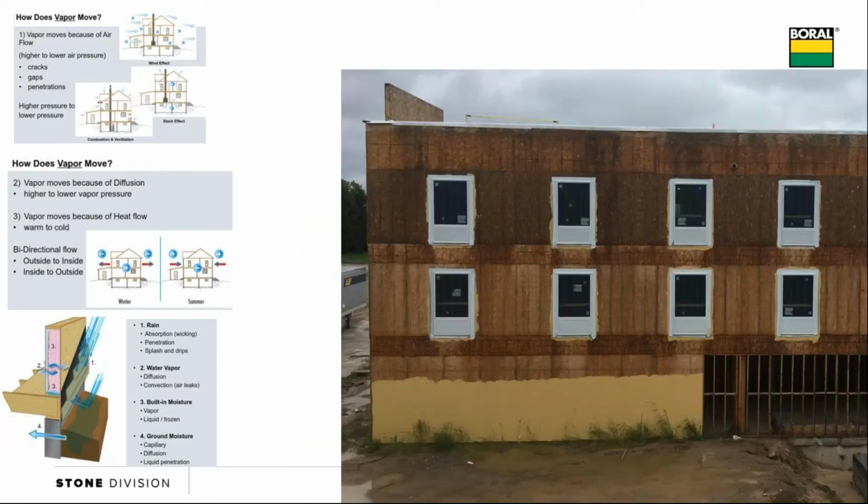And then finally this one, again, walking out of a hotel, this was a building next to it. You can see that OSB is completely saturated. If you could zoom in on some of the taping around that window, it's already starting to peel loose. I guess they could go out and redo all that stuff and make sure that it dries out before they apply to it. But those types of issues can be a problem.